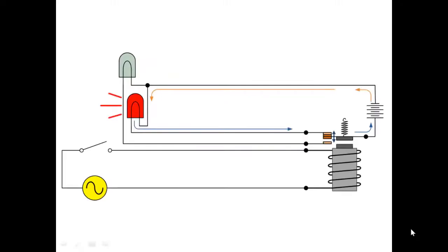Let's add our little relay diagram into an actual application, an actual circuit. We normally refer to that portion of the circuit which interacts with the operator as the public interface. You could say that there are three public interfaces to this circuit. The single pole, single throw switch, which the operator controls, and when he closes the switch, that energizes the relay. When he opens it, the relay de-energizes.